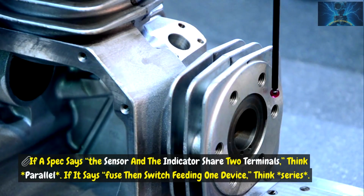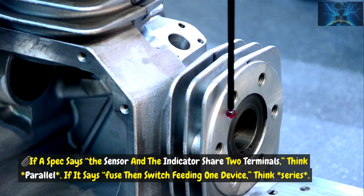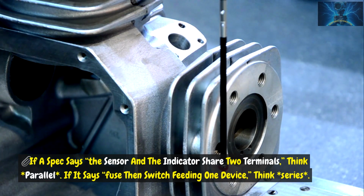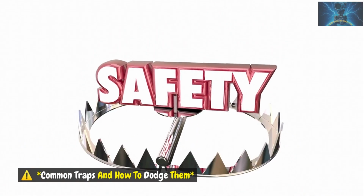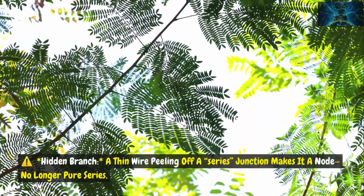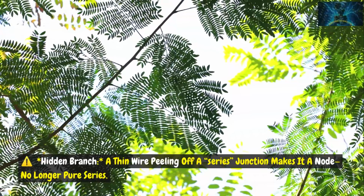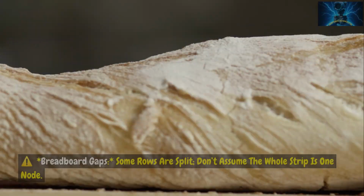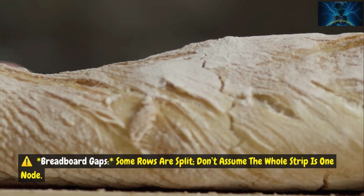If a spec says, the sensor and the indicator share 2 terminals, think parallel. If it says fuse, then switch feeding one device, think series. Common traps and how to dodge them. Hidden branch. A thin wire peeling off a series junction makes it a node, no longer pure series. Breadboard gaps. Some rows are split. Don't assume the whole strip is one node.